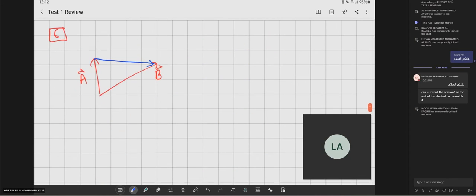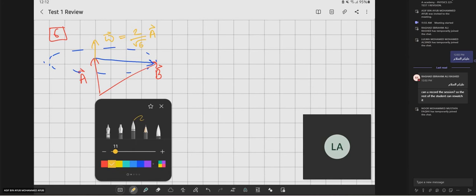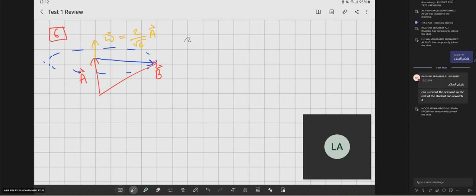Okay, so this is rotating like this, right? So again, A is angular velocity. They're telling you that it's rotating in the same direction, so omega is not changed. Omega we found in the last question, 2 over root 6 times (1, 1, minus 2). So we'll have, again, V equals omega cross R. But now R is AB, the vector AB.